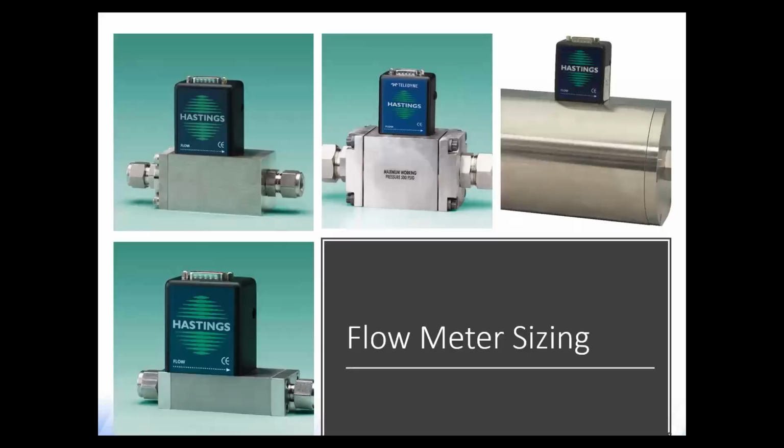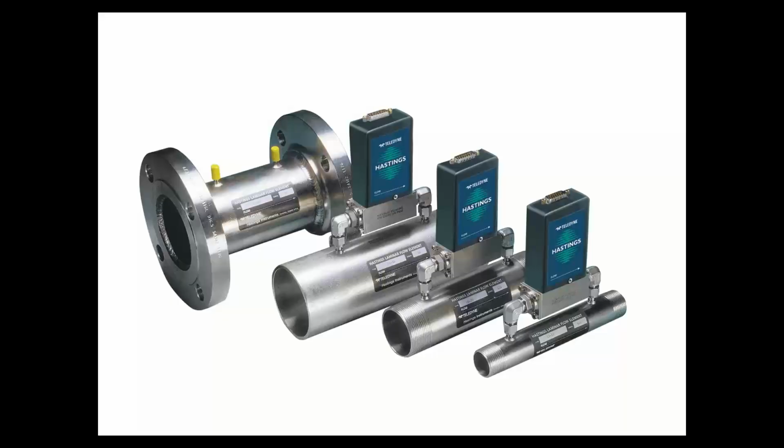So for your application, we want to ensure that we select the correct shunt and corresponding flow meter body to provide the desired full scale for the flow meter. And as you can see from these pictures, we have a broad range of models with various shunt sizes available. And we also manufacture laminar flow elements, or what we call LFEs. In these pipes, as shown here, there are corrugated passageways to ensure well-behaved flow.